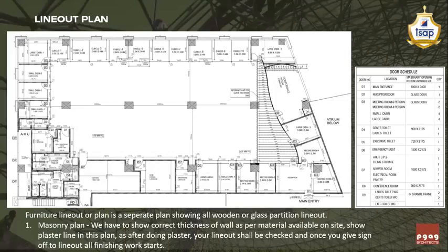And this is the language which we generally follow to convey what we actually require in terms of the design. That language is followed everywhere, and the contractor is also well aware of this language. So when he studies the line out plan, he comes to know where he has to keep the check dimension. For example, in this case, the reception, meeting room and all 3-4 cabins are going to get a stagnant dimension of 2.4, and then the last dimension of the large cabin is going to be a check dimension. So for him, it is very clear that he has to align this particular wall with the RCC column.